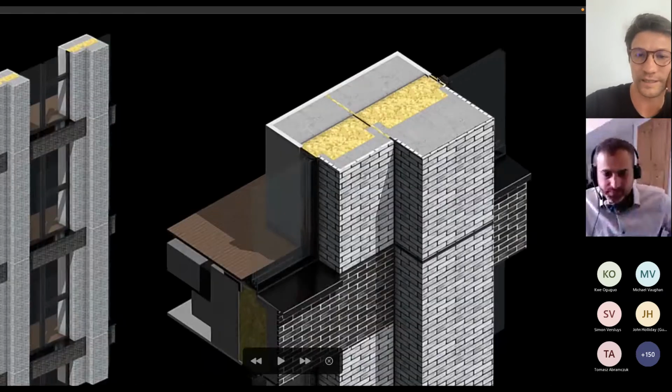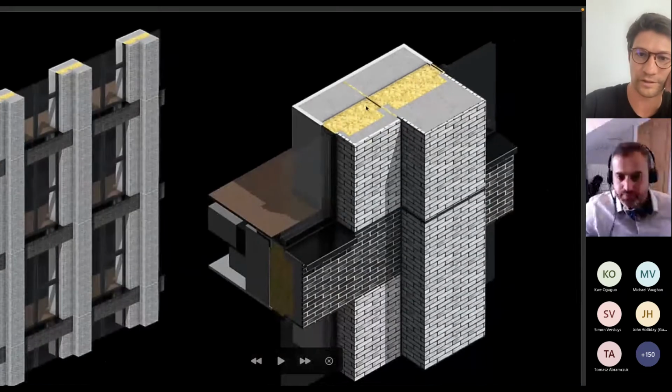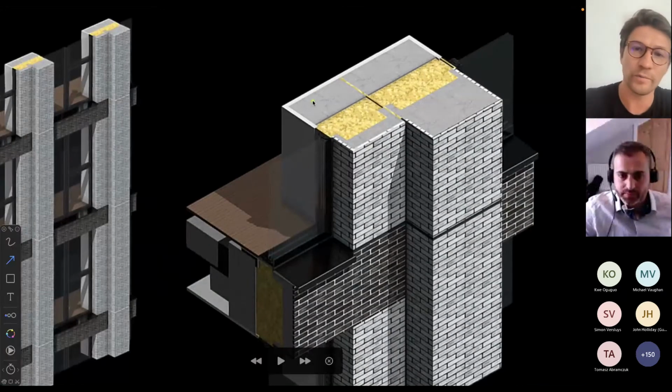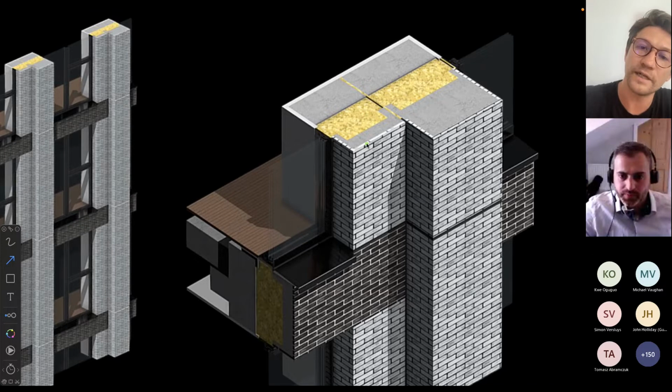This would be the ideal facade engineering element. When you have a precast concrete building, not just the facade, where the facade is built out of sandwich panels, as you see here, the dew point line is here. It's constantly within the insulation.